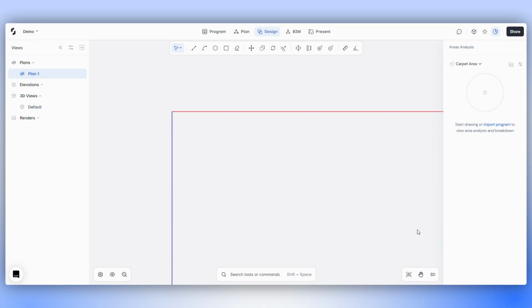In this tutorial, we'll guide you on how to create spaces using the draw tools available in the design mode. Begin by selecting one of the draw tools, starting with the rectangle tool, or use the shortcut R to activate it. Following this, open the object type panel. Under the design mode, the default object type selected will be a space. You can then choose to use one of the offset modes or opt for the freeform draw mode.